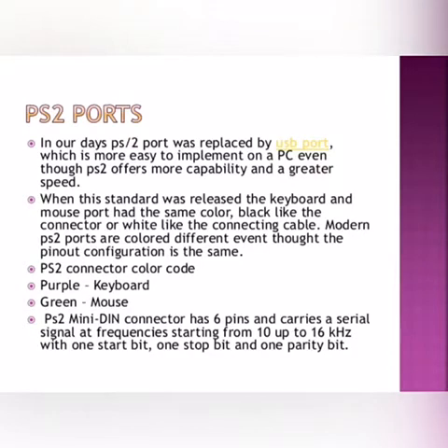When this standard was released, the keyboard and the mouse port had the same color, black like the connector or white like the connecting cable. Modern PS2 ports are colored differently even though the pinout configuration is the same. PS2 connector color code: purple for keyboard and green for mouse. PS2 mini DIN connector has 6 pins and carries a serial signal at frequencies starting from 10 up to 16 kHz with 1 start bit, 1 stop bit and 1 parity bit.